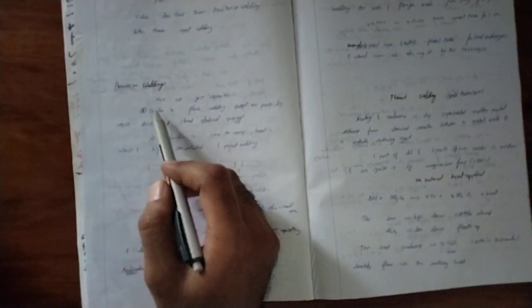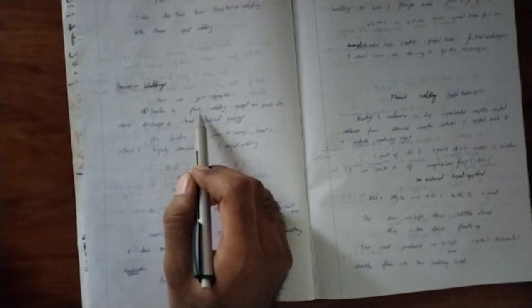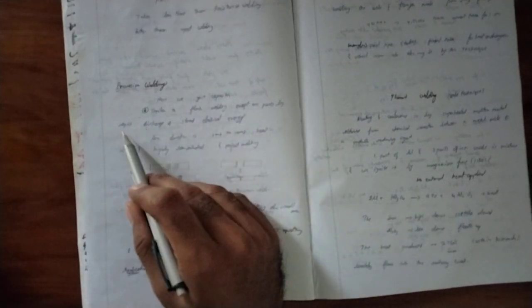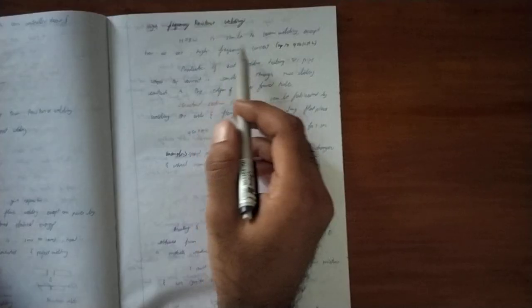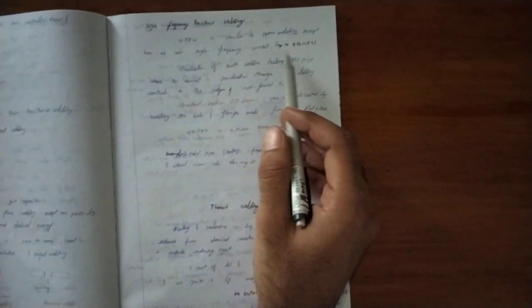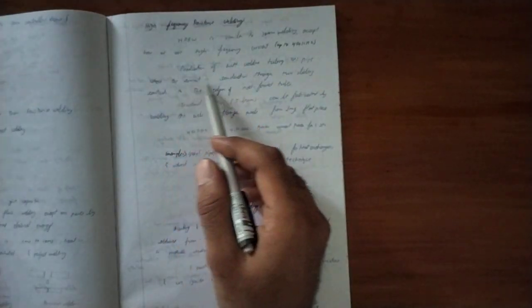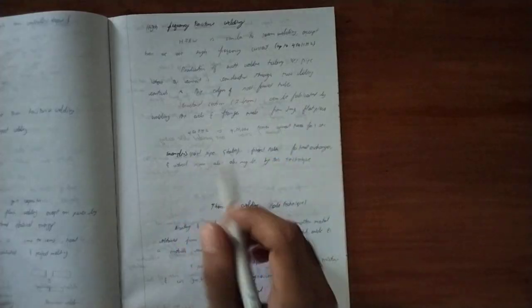And percussion welding. Here we use a capacitor. By using the capacitor we weld, similar to flash welding except the arc is produced by the rapid discharge of the stored electrical energy. Arc duration is just about 1 millisecond. Next one, high frequency resistance welding, is also the same. It is similar to seam welding except with high frequency current, and it is used in the production of multiple turbine pipe, and the sections of I-beams are fabricated by this.